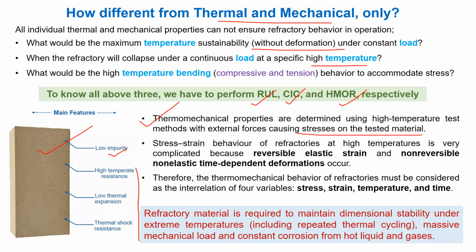Stress strain behavior of refractories at high temperatures is very complicated because reversible elastic strain and non-reversible non-elastic time dependent deformations occur. Therefore, the thermomechanical behavior of refractories must be considered as the interaction of four variables: stress, strain, temperature and time.